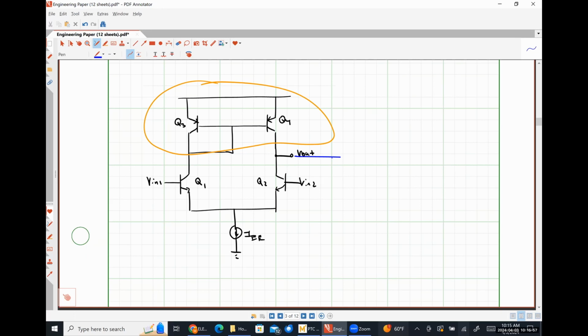We want gain, but we also want to drive the DC level back towards ground. So a PNP amplifier. If we do an NPN differential pair, we need to chain it into a PNP amplifier of some sort, and we'll bring that DC offset back closer to halfway between VCC and ground.